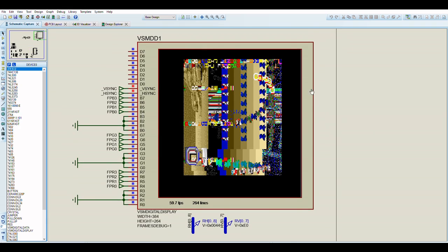So now I'm demonstrating that the hardware very comfortably renders 24 sprites up here and another 24 sprites down here using the multiplexing technique. In the off-screen part, it sets the sprite registers for the top half of the screen, and then as this raster line goes down, when it hits this position, it switches off the sprites.